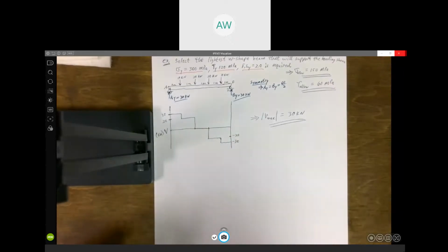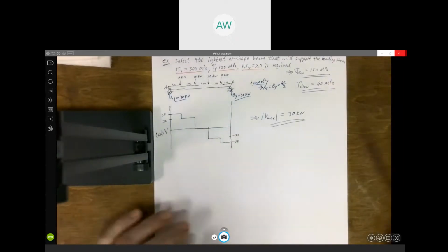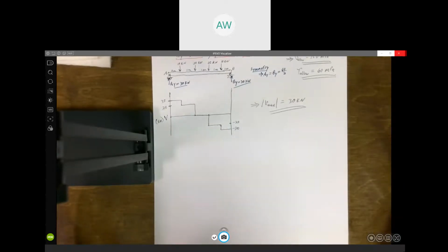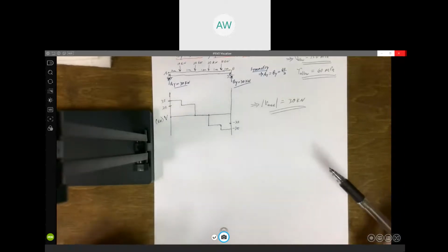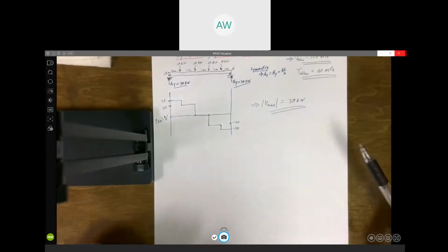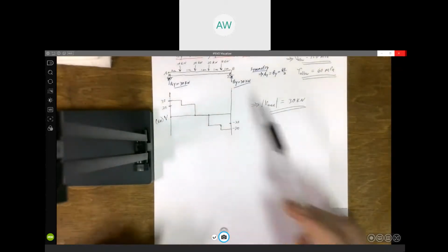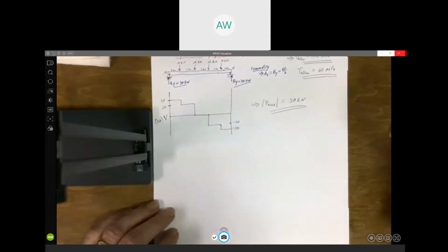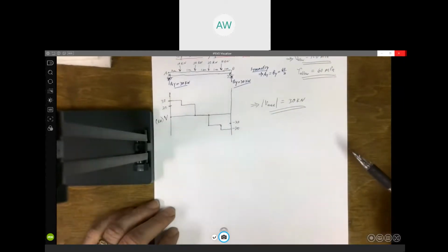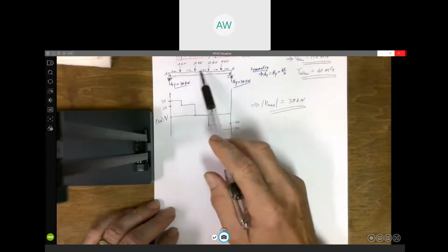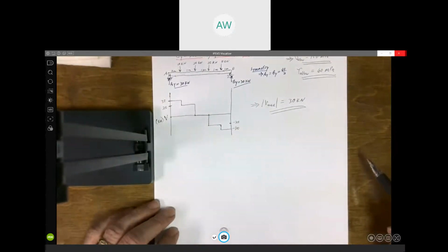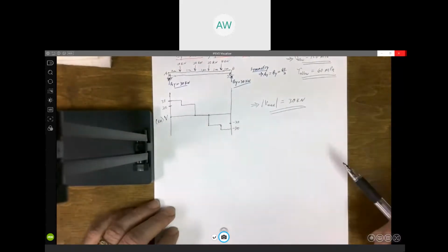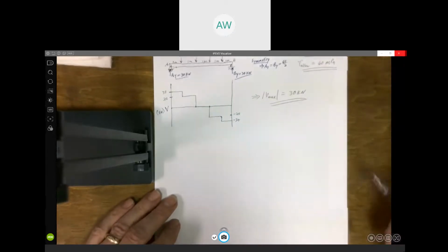At this point, I'll point out, I specifically told everybody for the test yesterday, this is how I wanted you to draw shear moment diagrams. I didn't want you to cut it and actually get the equations. If you do that, what took us less than a minute here now turns into several pages' worth of work. You'd have to cut this 1, 2, 3, 4, 5 times. It's not necessary. We can draw the diagram without doing that. Right? Any question about our shear diagram?